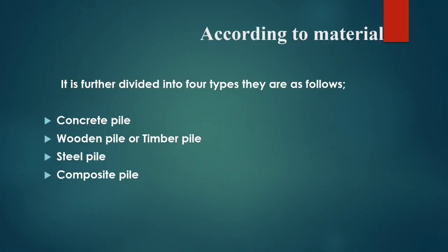Then, for some disadvantages of pile foundation. First, a pile can be damaged quickly by driving through stones and boulders. Second, piles can be attacked by marine borers in salt water. Third, a pile cannot be above ground level. Fourth, it is very difficult to know the actual required length in advance. Fifth, vibrations generated when piles are driven affect the neighboring structures. Sixth, heavy equipment is required for driving the piles. Lastly, piles are not suitable for low drainage. So those are some of the advantages and disadvantages of pile foundation.